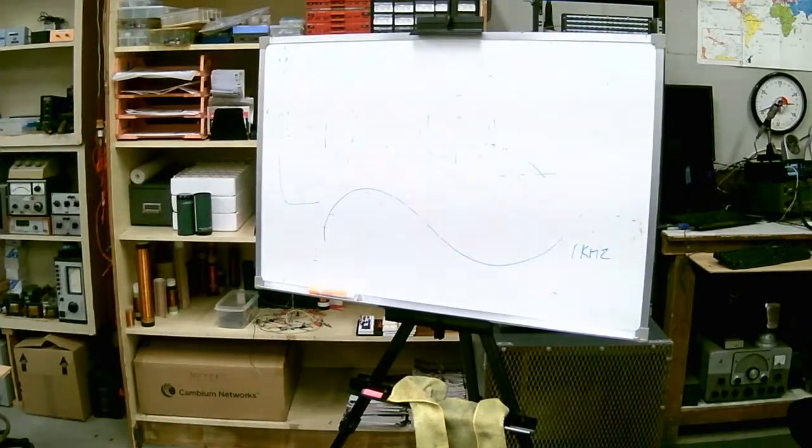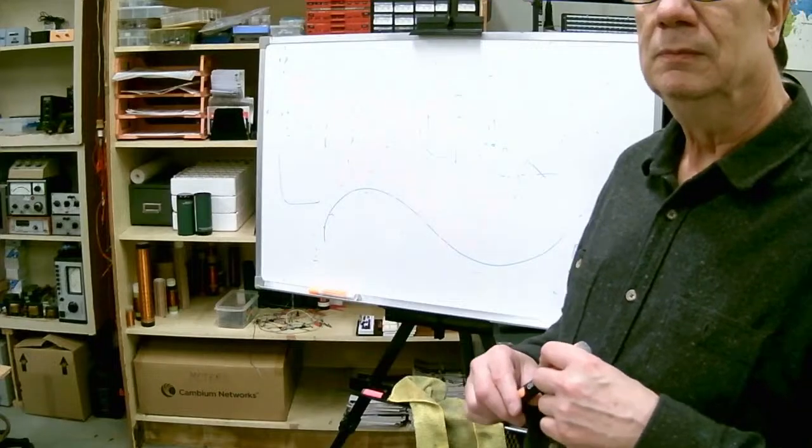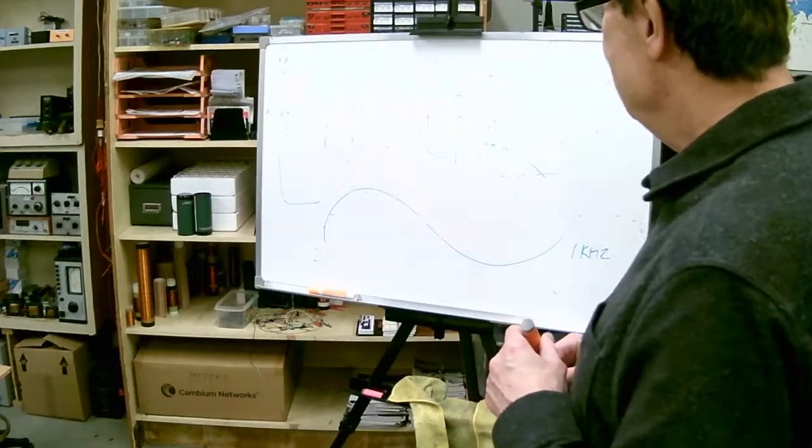And the way we do it in this one, we get this diode ring here, so that's actually a diode multiplier. At any point in time, it's the product of our carrier amplitude and the modulating amplitude. And that's changing the amplitude. Is the second orange line a useful signal? No, it's not.